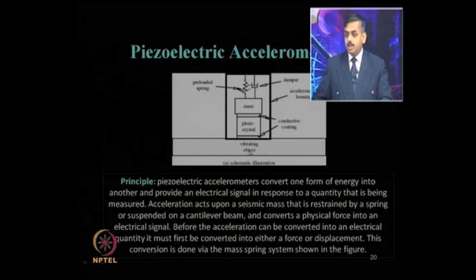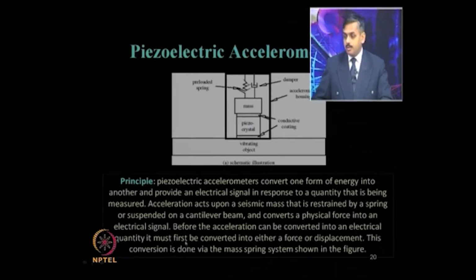So, whatever vibration comes, that vibration passes as an electrical signal, because it is passing through this piezoelectric material, and acceleration acts upon a seismic mass that is restrained by a spring or suspended on a cantilever beam. So, this mass is restrained on a spring, and converts a physical force into an electric signal. That movement is getting converted from this physical force to an electric signal through this piezoelectric material.